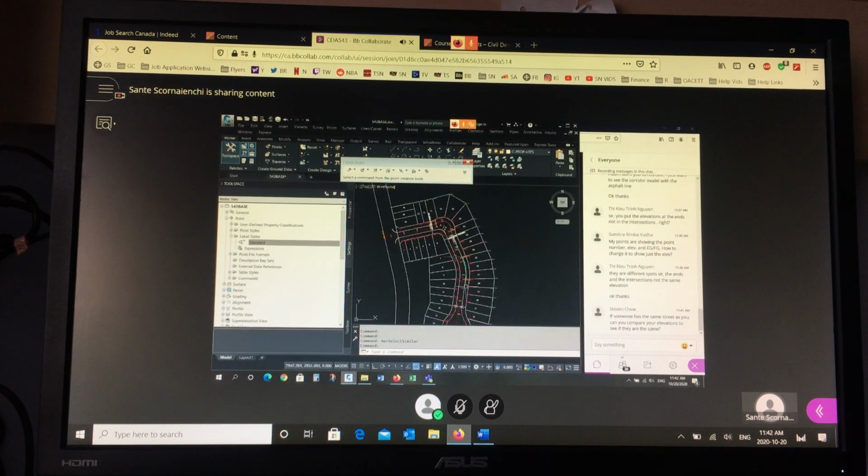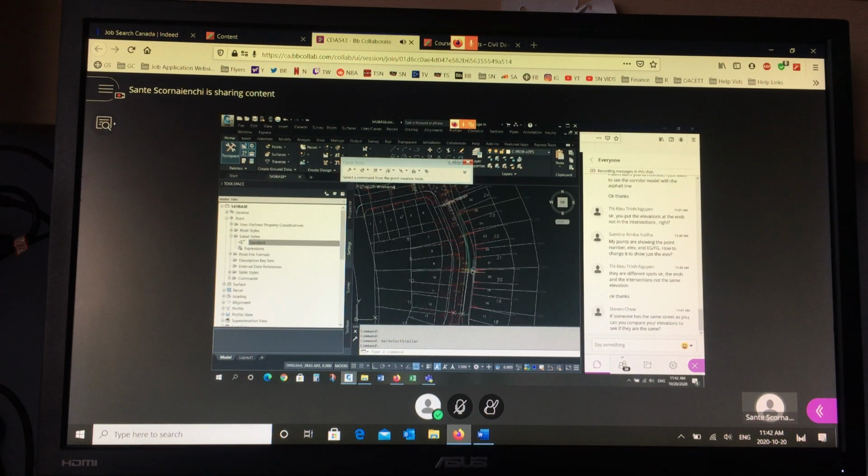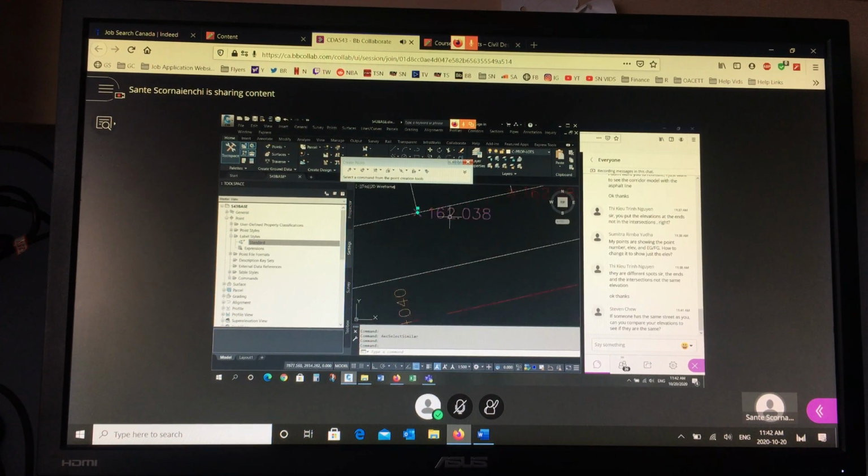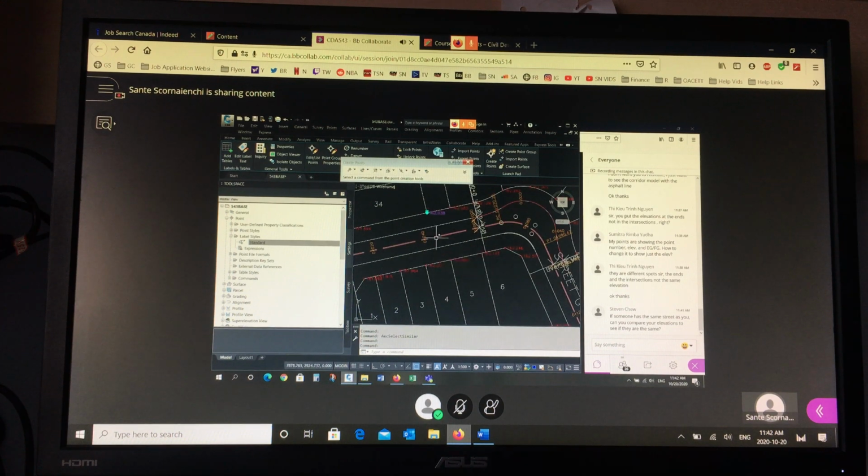I know these numbers are correct because my profile is correct, because my corridor is correct. And see how everything depends on the previous step. So if your design profile is correct, then your corridor model should be correct, then your corridor surface model represents correctly, and now you can be confident in these elevations. If you had to calculate these one at a time on paper from AutoCAD, you can get the station value of this point from the horizontal alignment. Then you can get the elevation of that point from the profile, and then you can figure out how to go from the center line down the pavement to the gutter and up the boulevard to get that elevation. Imagine doing that calculation for this entire site all the time. So that's the advantage of this technique.